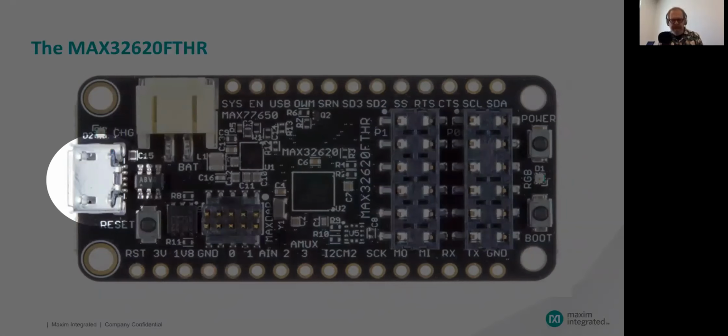you covered there. I say for the most part because by default we include a USB bootloader that uses this port to load your application. Now you can build your own application to use the bootloader, or you can just mass erase the flash and then use the SWD connector with a debug adapter to do flash programming.